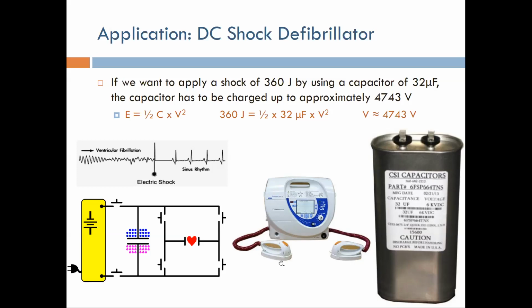It's very dangerous. So be sure that when you're working with a capacitor or a device like this, before you open it and try to do anything with this capacitor, you discharge it first. Make sure that it's discharged, otherwise you can be in danger. This is one of the important things I wanted to talk to you about. Electrical safety is not just for AC. Whenever you have a high enough voltage like this, you have to be really careful around it.